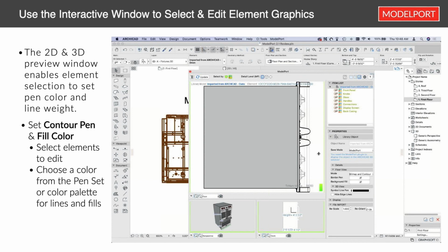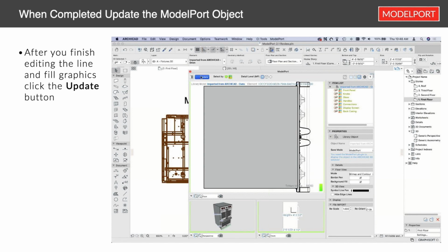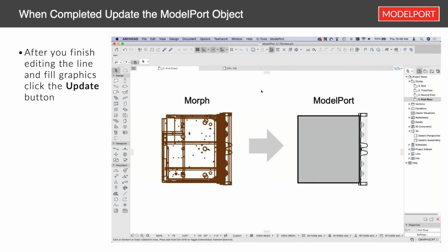Poly reduction basically takes your polygons, let's say you've got 100,000 polygons, and reduces them by 70%, 50%, 20%, whatever you want to set it to. It's going to decimate, if you will, those polygons in order to reduce them so you don't have as many. That means on some of the curved surfaces, they won't look quite as cleanly curved, which for many objects doesn't matter unless you get up really close.